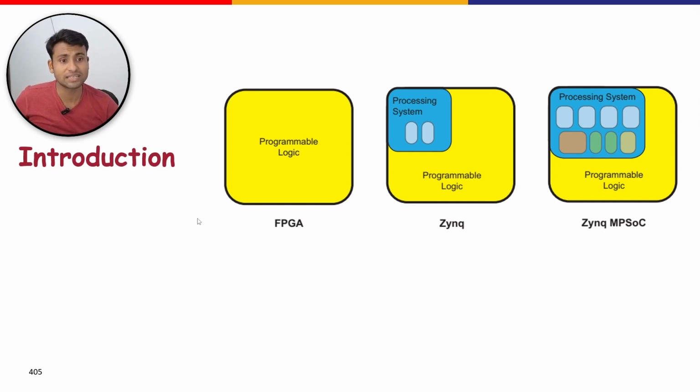So, discussing the Zynq MPSoC device families, all Zynq MPSoC device families contain what is called the PS. You can see that the Zynq families contain the processing system in both cases, and the PS is a dedicated and optimized silicon element within the device containing many different processing units and platform management and security systems. The PL, on the other hand, which you see in yellow, exists as a programmable region of FPGA fabric, capable of accelerating arbitrary logic functions and reconfigurable during runtime.